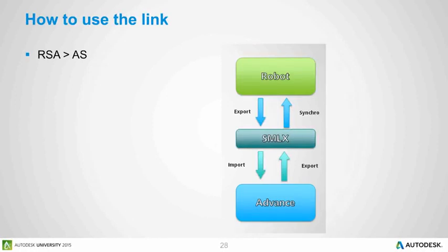Well, you may also create a model in Robot and send it, or the entire model or its part, to Advanced Steel. This option is intended for production of fabrication drawings, but it also allows a structural engineer to send information about design forces for connections for which a fabricator is going to be responsible. Mind that for a group of connections created in Advanced Steel, you should name the connection with the largest forces as the master, because there is no code checking for forces imported from a model for slave connections.